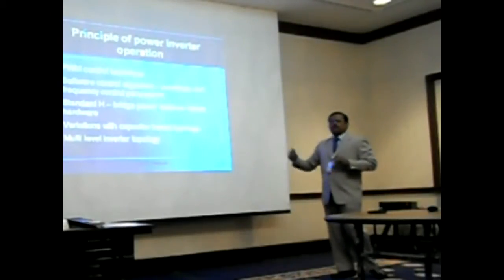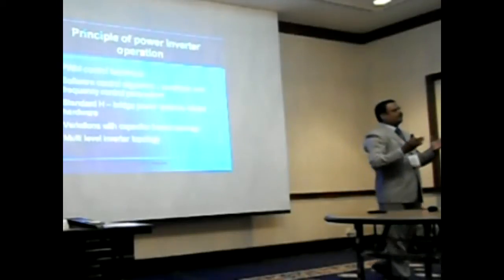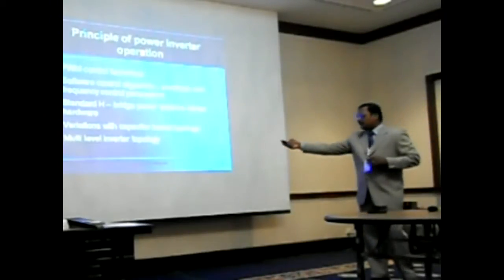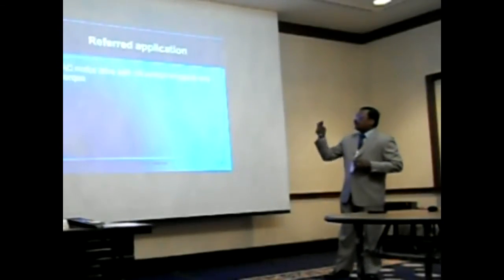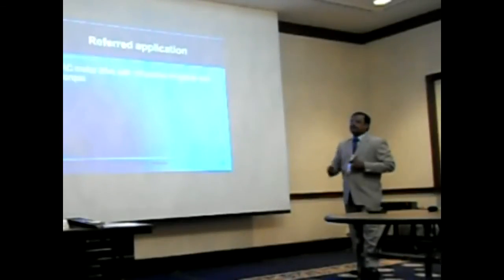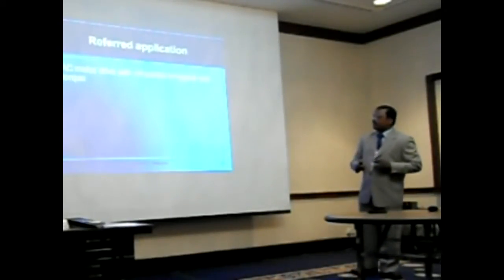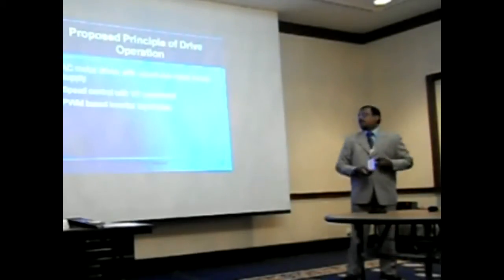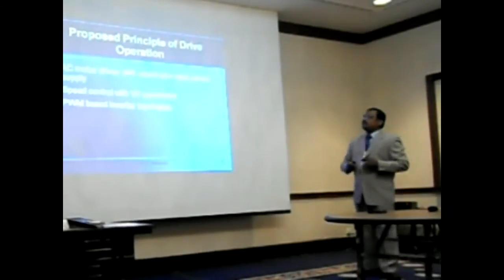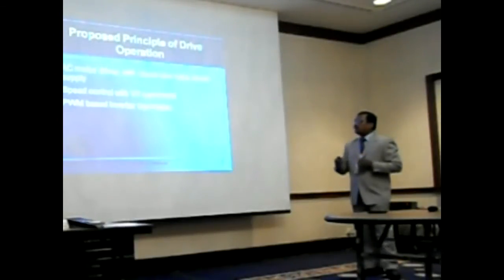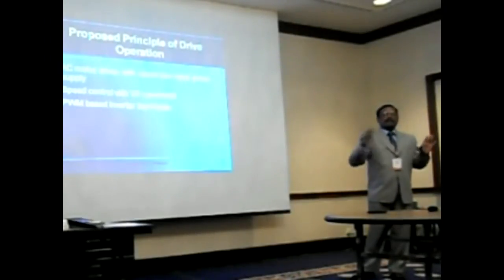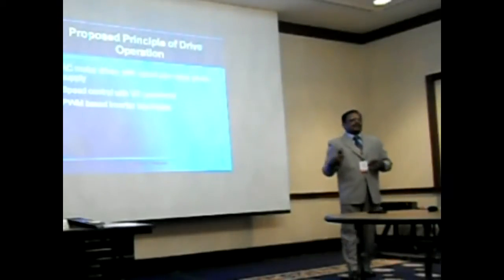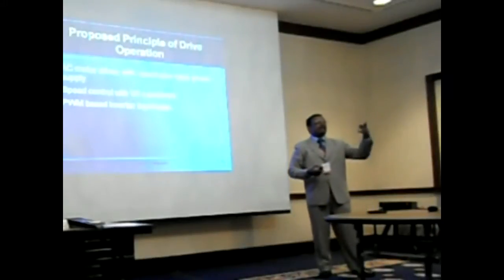And the circuits again, with motors, you have a single phase motor, three phase motors running with various capacitor connections and all those things. And now the latest technology research work is going on in multi-level inverter topologies. The application which I am referring to here is the AC motor drive with voltage by frequency control constraint for speed control of AC motor. The principle which I am presenting here is a comparison of a raised sine wave with the normal sine wave. What we get as power here is a normal sine wave, which is applied to the motor for running the motor. But what I am trying to present here is a raised sine wave that is firing the motor.